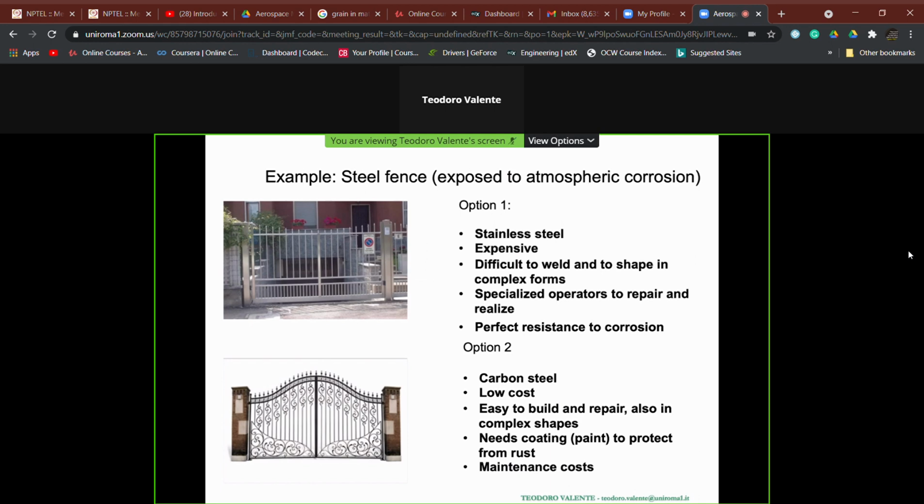of atmospheric corrosion, because atmospheric corrosion is a corrosion phenomenon based on the electrical charges exchanges. And if we put a chromium oxide layer on the surface of our furnace, that is a ceramic material which is not electrically conductive, and thus the so-called electrochemical corrosion will not occur. But this would be, just looking at the material selection, let me say, one very good choice.